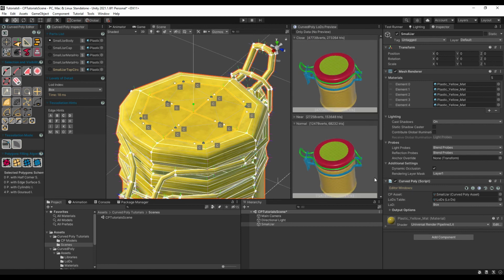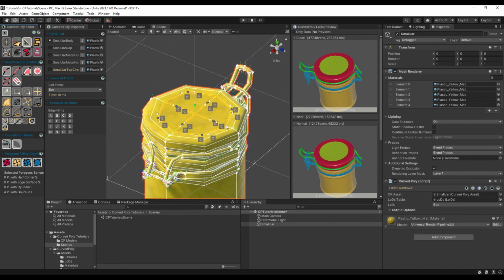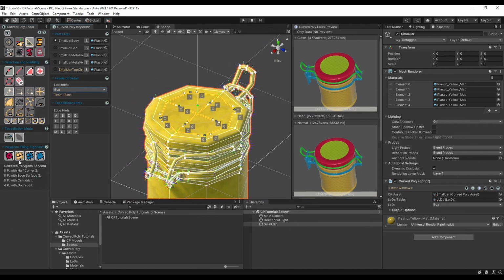One last thing. For a complete interaction with the model, we have added to Tessellation Tools a control over polygon filling algorithms, not different from the one used in Shape Tools. With this control you can correct potential issues generated on polygons after the change is made to hints and level of details, and also try different combinations of filling algorithms with tessellation data, in case you need to lower the computation time of tessellation.